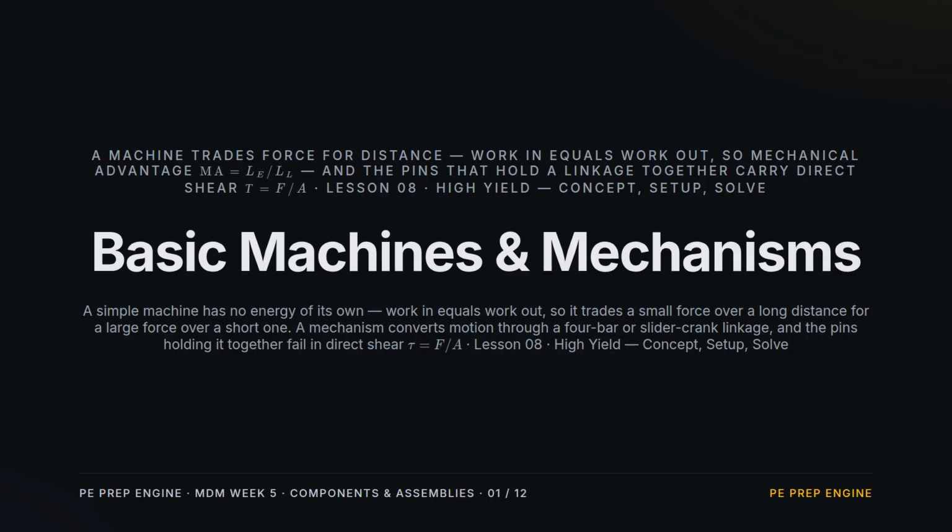Week 5, Lesson 8, Basic Machines and Mechanisms, plus the pins that hold a linkage together. 3 ideas. A machine trades force for distance, with no energy of its own, so work in equals work out. A mechanism converts motion through a linkage you analyze with instant centers. And the non-threaded connectors, pins and retaining rings, carry direct shear. We'll close with the degrees of freedom count that tells you how many inputs a mechanism needs.